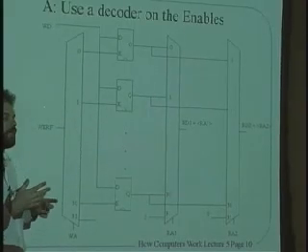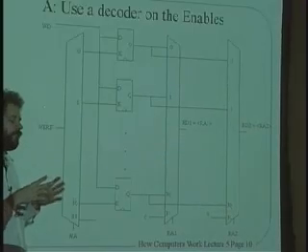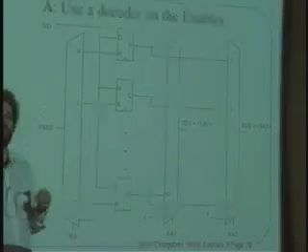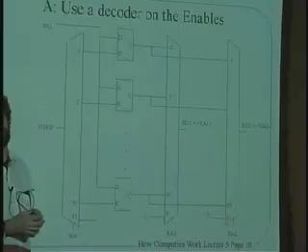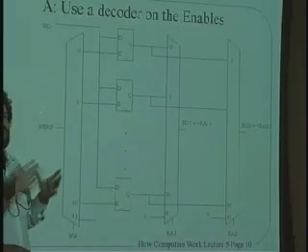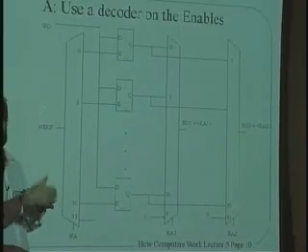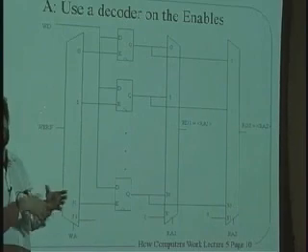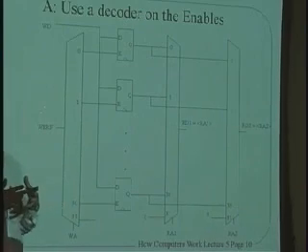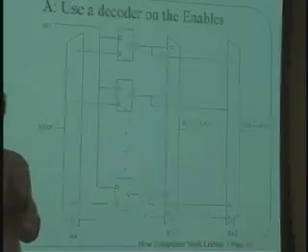But the instruction set architecture that we've designed really only writes to 1 destination at any given time. The opcodes always operate on RA, RB, putting the result into RC. So there's really no mechanism for saying I want to write more than 1 register at any given time.